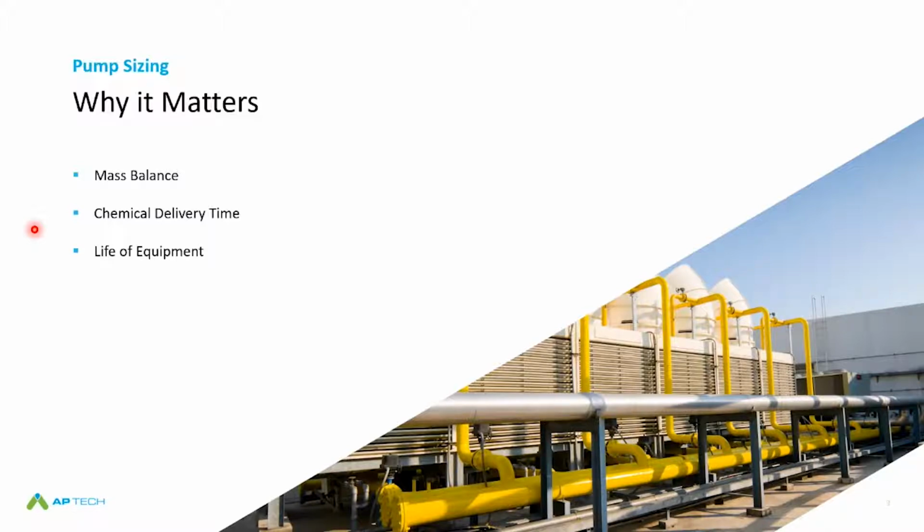On any of the products that you're using out in the water treatment world, they're going to have an application dose rate when it comes to either continuous or shot dosing. They're all going to have different specifications, and that's for any type of chemistry, whether it's liquid or solid. So in order to ensure that you're doing a proper job or a proper treatment and doing it responsibly, you need to be carrying out mass balances to ensure that you are feeding the appropriate amount of chemistry.